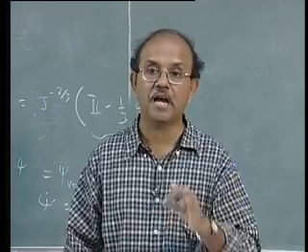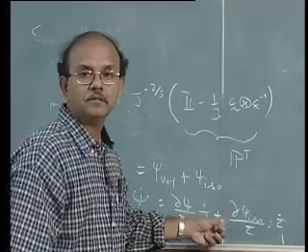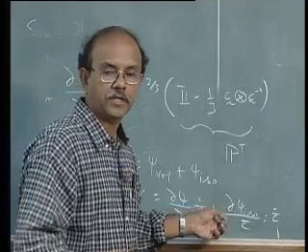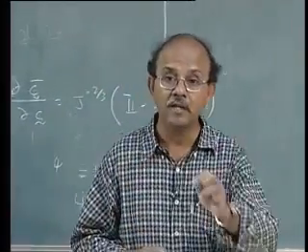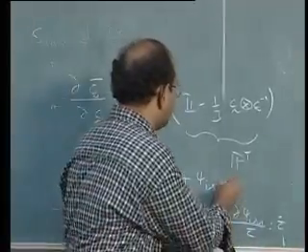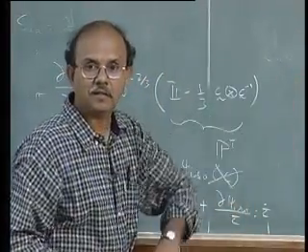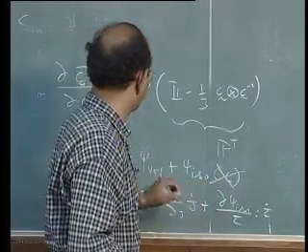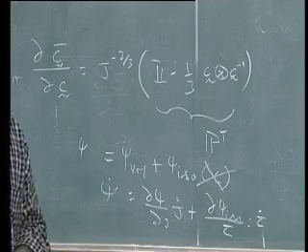So when I want to look at the strain energy function, I have to write this in terms of the isochoric part, or C bar. I can't write this obviously in terms of C, because C has that compressible part, and that compressible part has been removed and is put here. That's all.